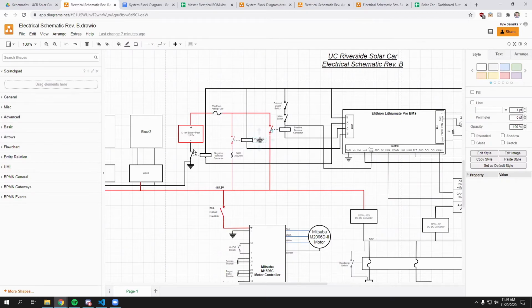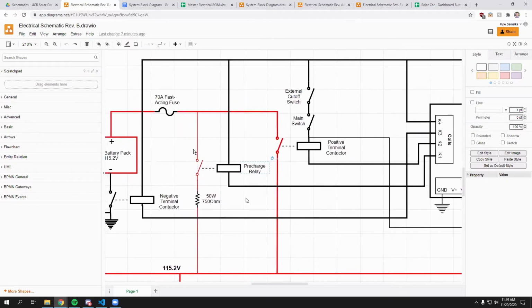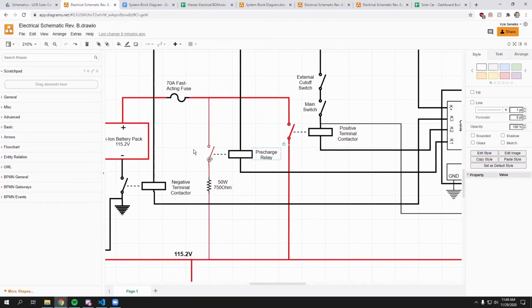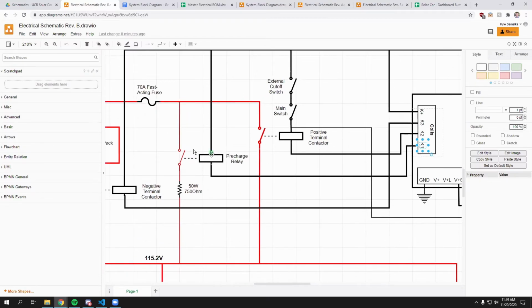Yeah, so a relay is just a switch. It's a way to physically isolate one circuit from another for safety reasons. So you can control a really high voltage bus like this, 115 volt, and have it completely physically isolated from this low voltage line. This low voltage line is, I don't know, probably 5 or 12 volts or something, and it controls this switch, which closes to turn on this line.